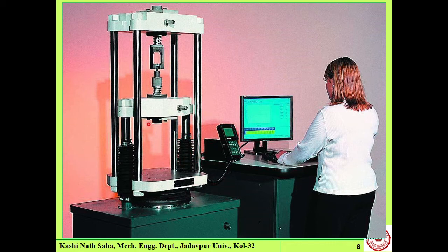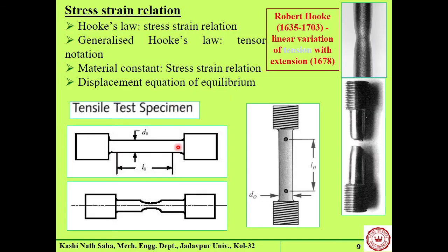Here this movement comes from this hydraulic cylinder. This is the power bank which contains the high pressure fluid, and when we release the valve, the fluid pressure goes through this ram and this cross arm, which applies the particular force to the specimen, and there would be some elongation of this particular specimen from movement.